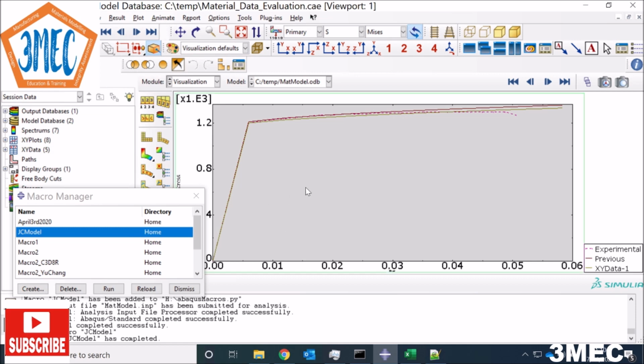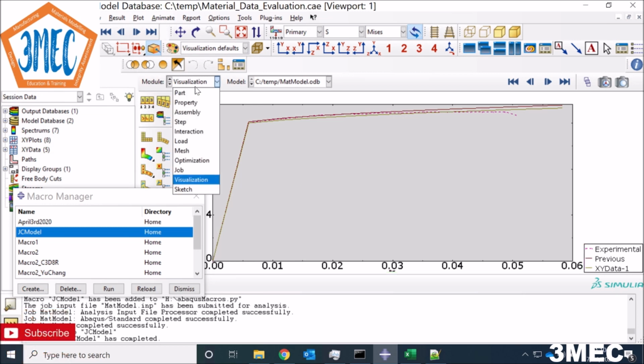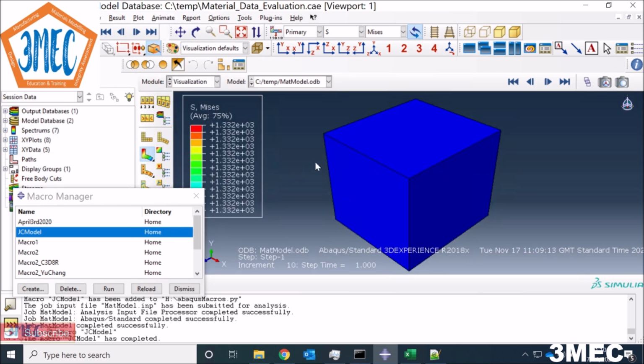You need to do a lot of runs, and based on that you can identify the parameters, and then once you have identified the parameters from a representative uniaxial test as discussed today, you can use it for any other real case which you have. Imagine if you have strain rate dependency, so you have test data from different strain rates, or data for different temperatures, or a material model with more complicated behavior which requires a huge number of parameters rather than only 3 in this case. Then it's a very tedious job to do manually, as I showed you before today. So in those cases it might be a good idea to use some kind of automatic identification procedure.